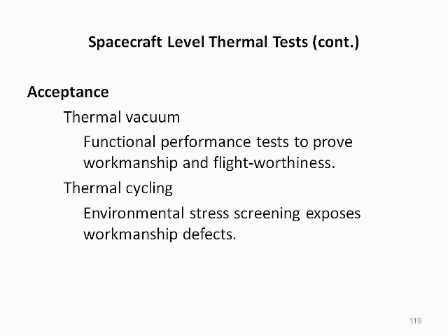At the acceptance level, thermal vacuum and thermal cycle testing are performed. Thermal balance testing is a good idea, but is not always required because the thermal design and thermal math models will have been previously demonstrated at the qualification level. During acceptance thermal vacuum phase, functional performance tests are conducted to prove workmanship quality and flight worthiness. This is different than the qualification thermal vacuum test where the design robustness is being proven. During the thermal cycling phase, temperature cycling provides stress screening to expose workmanship and manufacturing process defects.